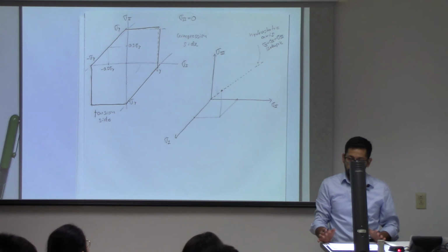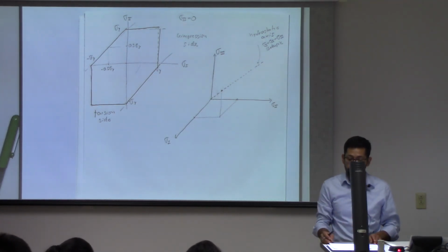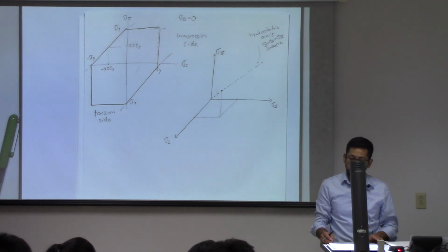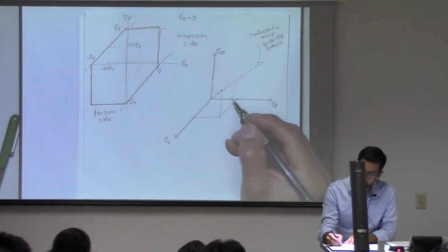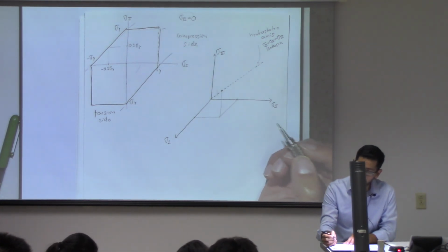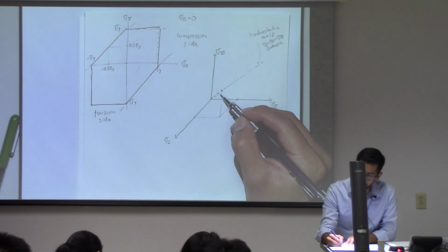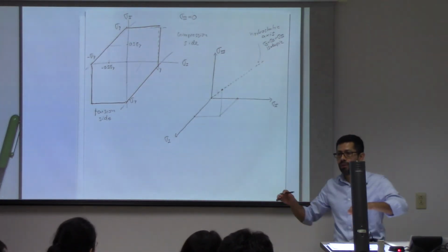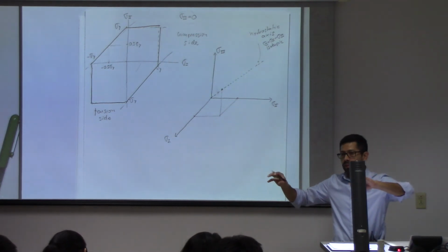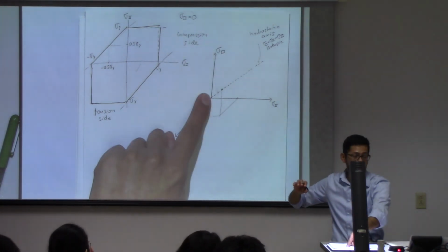All right. So if you do not have an isotropic state of stress, then what you can do is you can plot that, and you will see that that's going to be always a combination of an isotropic. As you remember that we did before, we partitioned the state of stress into an isotropic tensor and a deviatoric tensor. Well, in this case, it's the same.